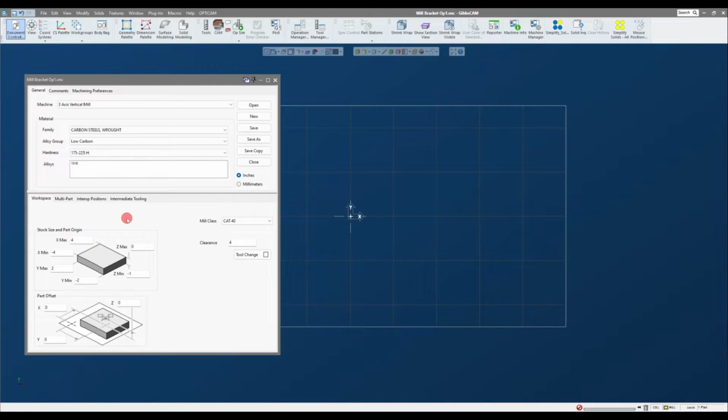Now, you will also have to put in the right tool material, number of flutes, coatings, all of that to generate the best feeds and speeds. Now, if you're generating your own feeds and speeds, you don't necessarily need to worry about this too much. You can put in your own cutting parameters as you go along, and GibbsCAM requires a bit less information if you're generating your own cutting parameters. If you're using it to generate cutting parameters for you, you do want to give it the most accurate information possible to get the best starting cutting parameters for your tools and the material that you're choosing.